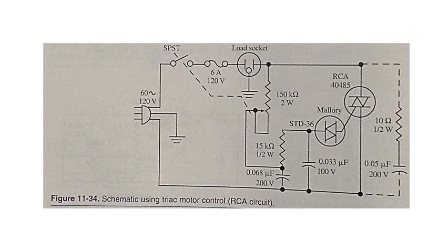The universal motor. The laws of magnetism were used to explain the operation of the DC motor. But will a DC motor operate on alternating current? The answer is yes, to a limited extent. Motors that operate on either AC or DC are called universal motors. With an alternating current, the poles of both the field and armature windings will periodically reverse.